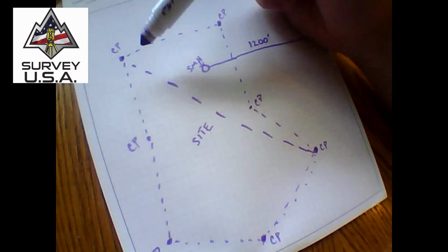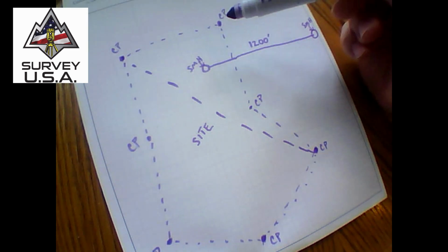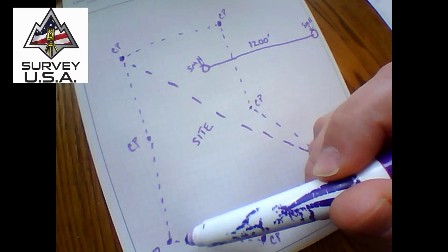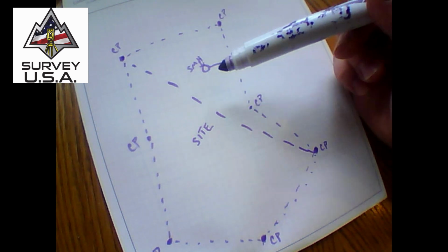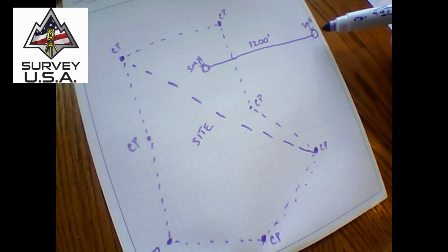But now I look at this almost as a basis of bearing, controlling the orientation of the site, controlling the entire site, left or right of the line. You're not going to have any distortion. You shouldn't have any, or at least enough to be concerned about, going to anywhere on this site, or even going out here to this sanitary manhole and staking this whole line. That's how I do site calibrations.